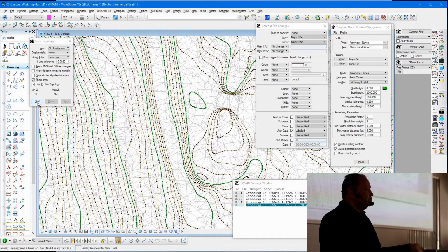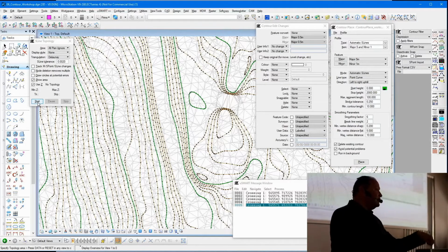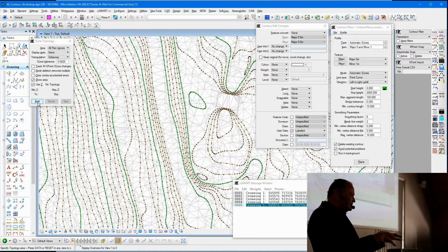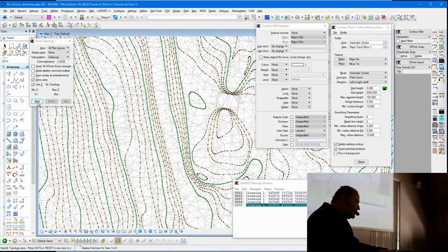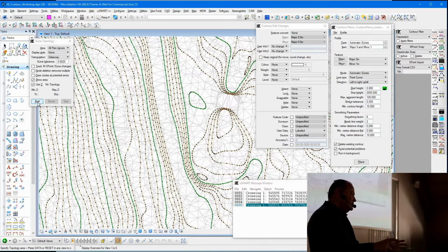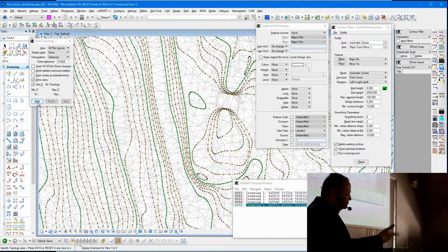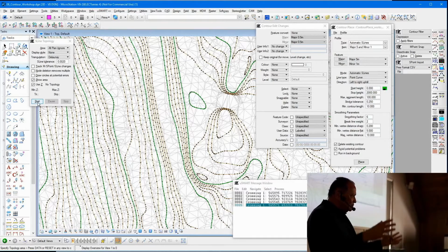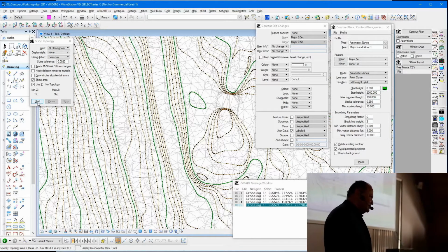But that doesn't stop you from switching on your triangle tracking again, and it will give you the height at that point. But very often you're trying to find a happy medium because your DEM is not that good in that area. It's a little bad because, if you were running drones, there was a tree there, so now there's no DEM under the tree. But for LiDAR, you would have got another return from the ground, so you then switch off your tree. But for autocorrelation, you would have the tree canopy, for example, if it was dense, and you might not have a point on the ground. So now you're sitting and you're feeling it, to tell you the truth.